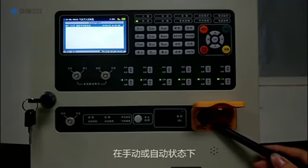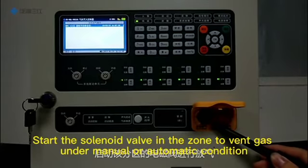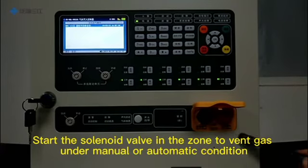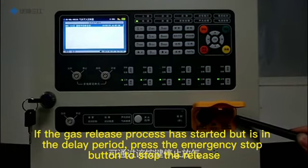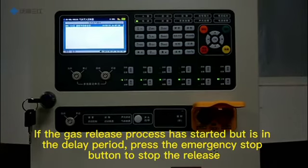Emergency start button. Start the solenoid valve in the zone to vent gas under manual or automatic condition. If the gas release process has started but is in the delay period, press the emergency stop button to stop the release.